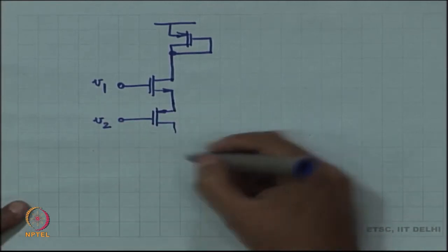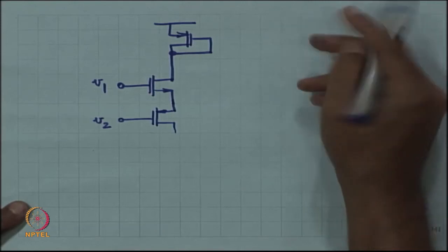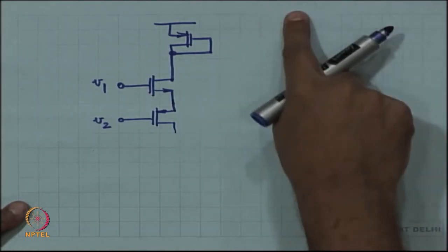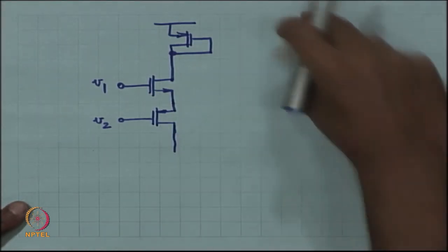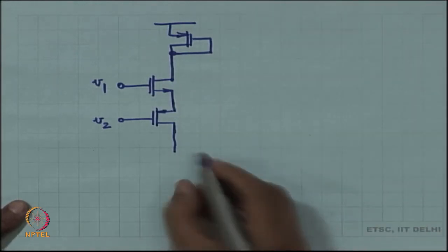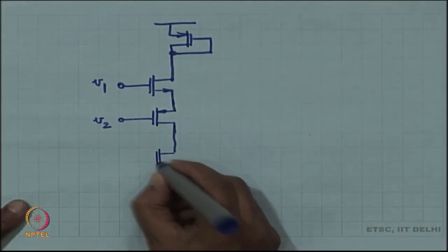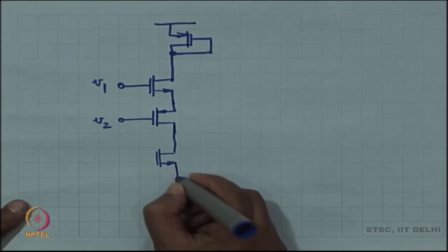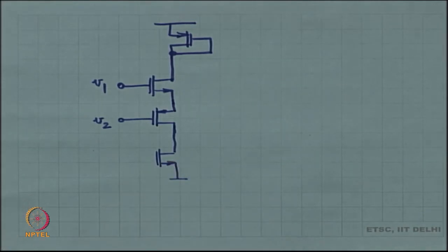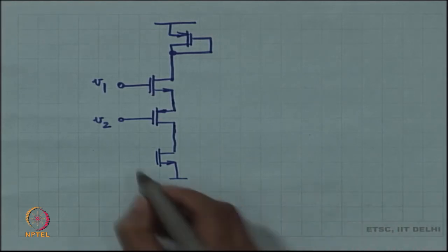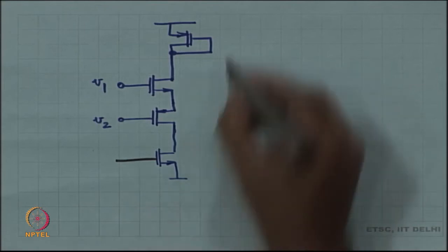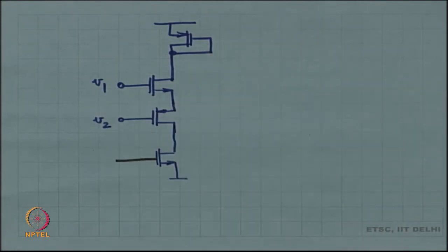Okay. And then finally on top there was a PMOS device, right, and I will fold that also downwards, and now I will draw it as an NMOS because it looks nice, with the caveat that the gate of this NMOS is actually connected up here.